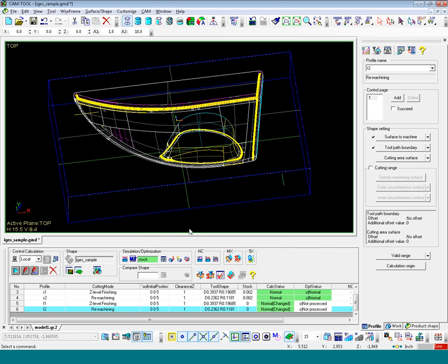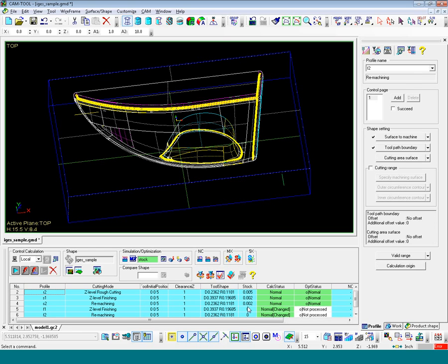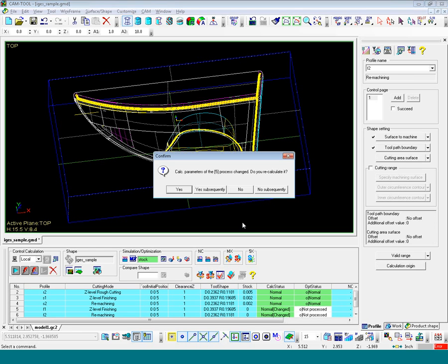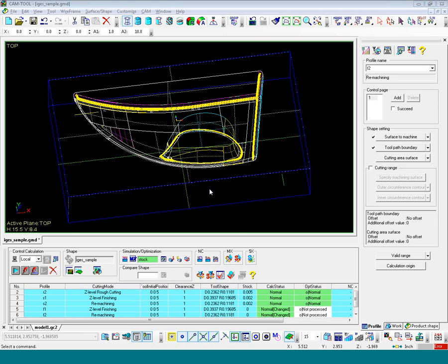So now let's select all the toolpaths and send them off to calculate. If you want to select all the toolpaths, right above the number column there's a NO. box. Click on that box, and it'll select them all. And then we can just hit the play button and say Yes to All, which means yes, do them all. But because the last toolpaths are the only ones that actually needed to be processed, that's all it's going to do. And when these are done, we can take a look at what the final result of the toolpaths is.